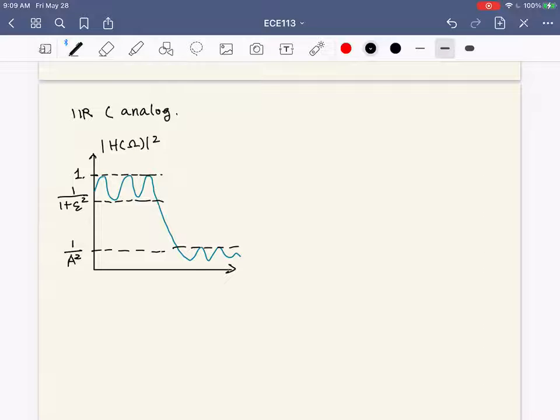So usually we can consider it in the S domain, which corresponds to a continuous time domain. And our unit here is big omega, and its unit is rad per second, if you remember. Okay, so you see that when the passband ripples end, it maps to a frequency called big omega p.